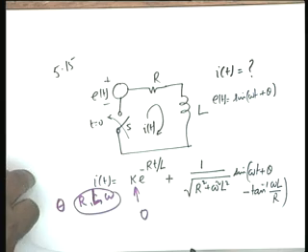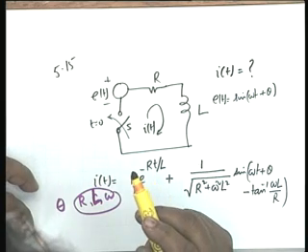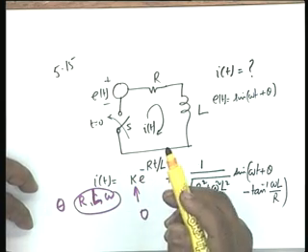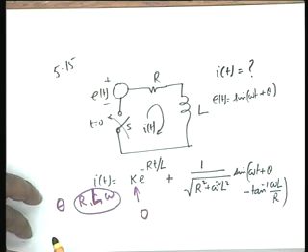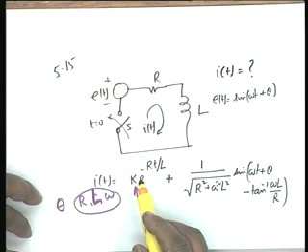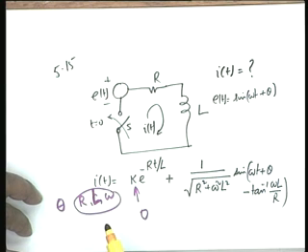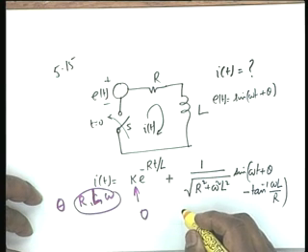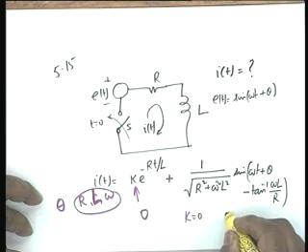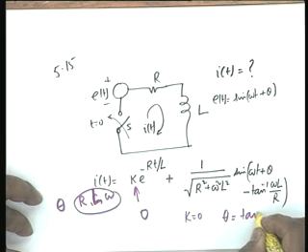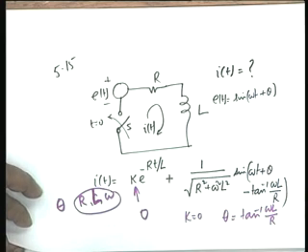Now, you notice that when the initial condition is 0, so I of 0 is 0, that means k would be equal to minus this quantity with t equal to 0, and isn't it obvious that k would be equal to 0 if theta equals tan inverse omega L divided by R? Yes, of course it is obvious.